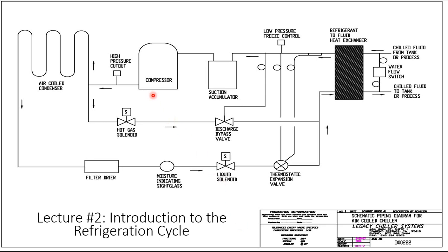Okay, so let's always start at our compressor. As we mentioned earlier, this is the heart of any refrigeration system. What this compressor does is it creates a pressure difference. In just a few minutes, I'll cover what exactly is going on here. The next thing we have is our condenser. Again, what the condenser does is it takes whatever energy has been absorbed by the refrigeration system and gets rid of it. Usually this is done into the outside air, but not always. Sometimes it's into a water source or something like that.